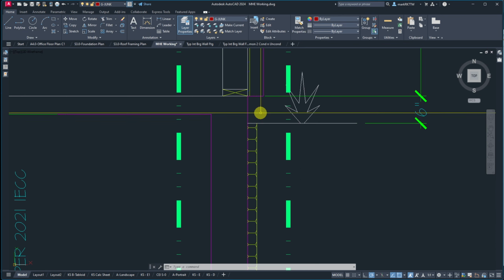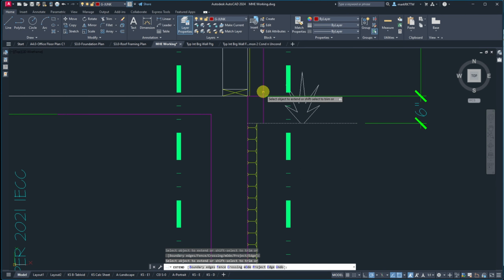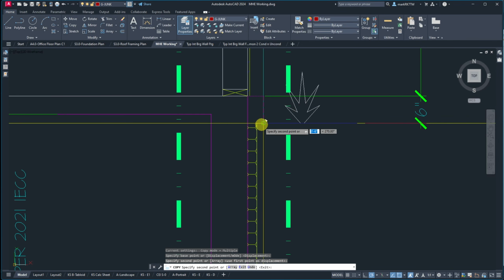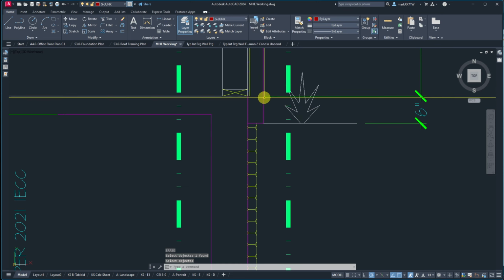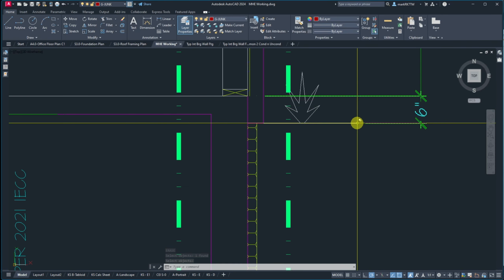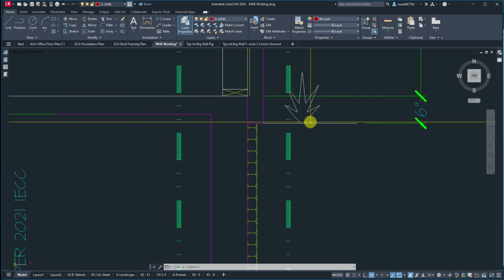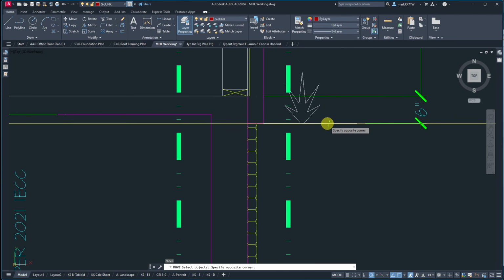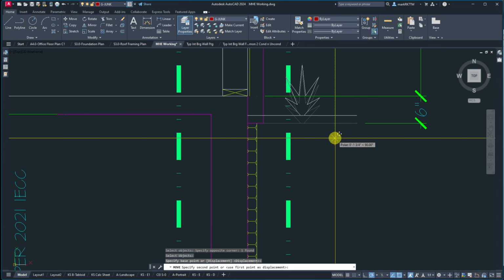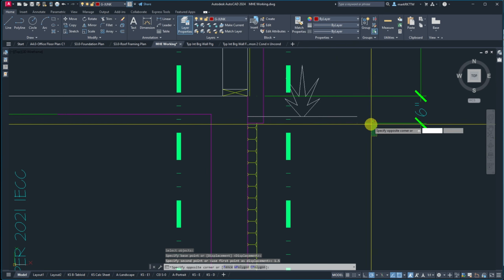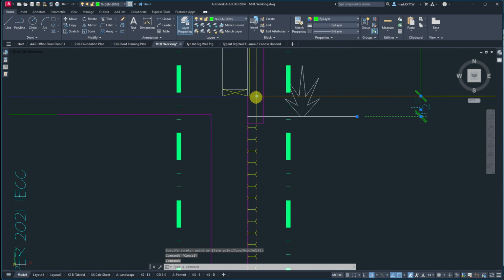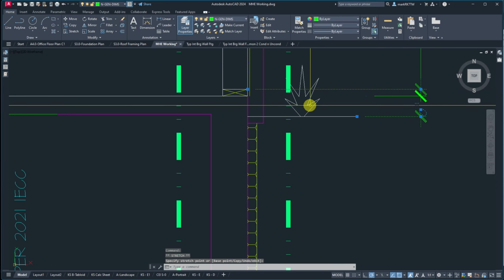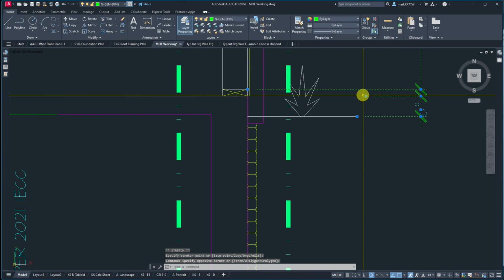We're bringing the stone down like this. So I can basically move that down to here and get rid of this. The 6 inches from the grade to the bottom of this is not true. I actually moved that down too far. I need to move this up 1.5. Let's get this rule right. This rule is to here because I'm using a pressure treated sill plate.